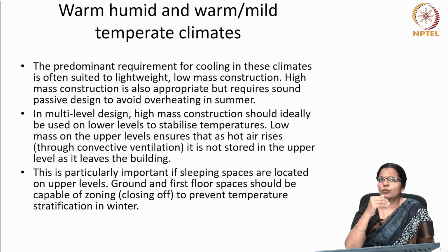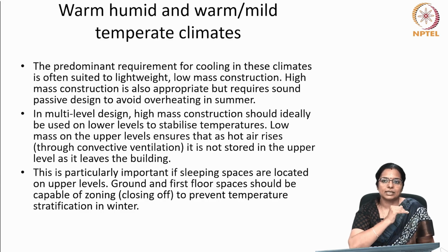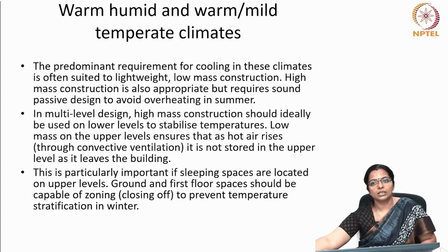What should you do in warm, humid or warm and mild temperate climates? The predominant requirement for cooling in these climates is often suited to lightweight, low mass construction. High mass construction is also appropriate but requires very sound passive design to avoid overheating in summer. In multi-level design, high mass construction should ideally be used on lower levels to stabilize temperatures.